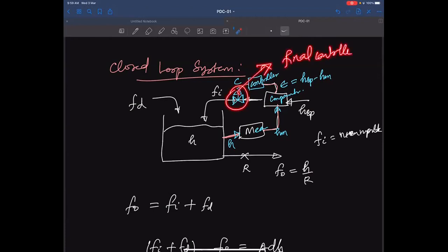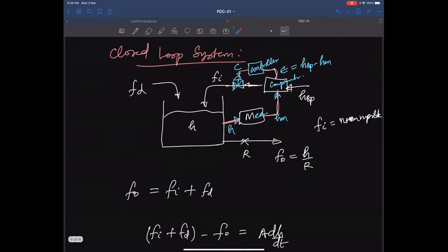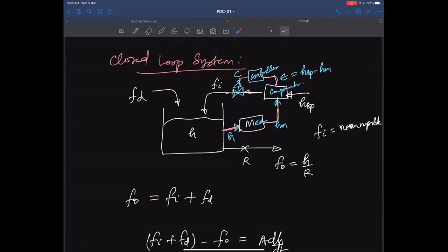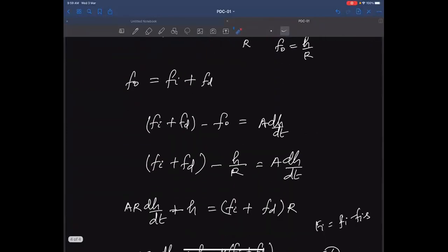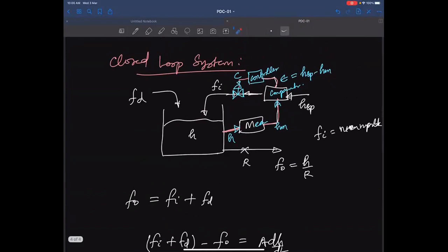Most of the time we will have the control valve as the final control element, because in the end we are simply adding mass or energy to the fluid. So this is not simply a flow diagram; it is material flow and also information flow. This is one piece of information, and there is another. The controller again receives information and acts on the control valve. These are all some sort of electric and pneumatic signals, and the measurements are electric and pneumatic signals too.